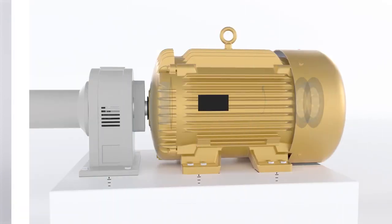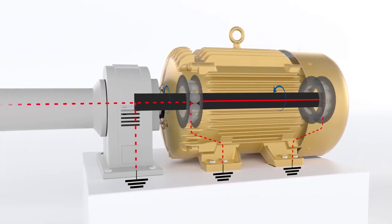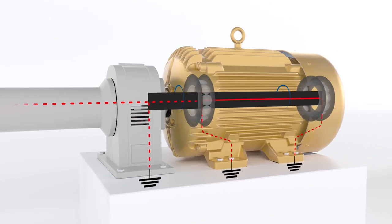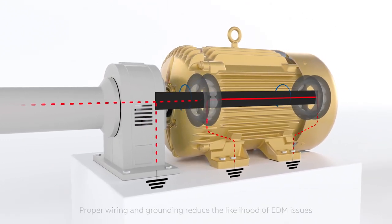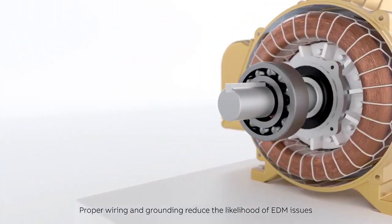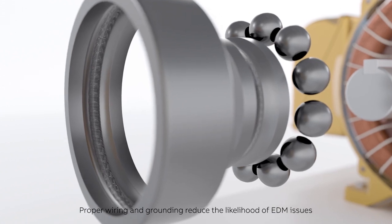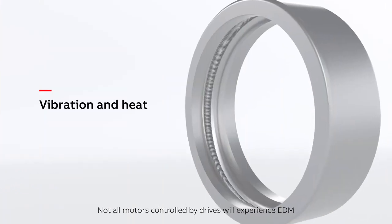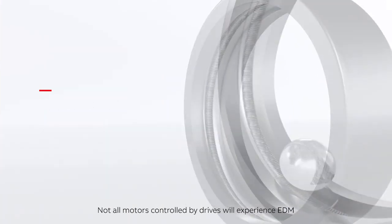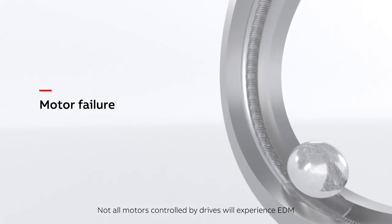Common mode voltage builds up across the bearings due to the dielectric effect on the bearing grease and will eventually discharge through the bearings in what is referred to as EDM, or electrical discharge machining. Over time, this continual arcing will cause damage to the surface of the bearing race, resulting in vibration and heat, loud operating noises, and eventually motor failure.